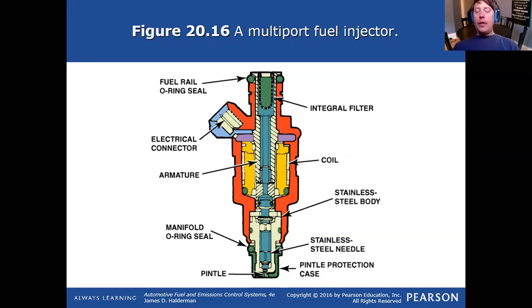That's one of the ways that injectors can go bad. If the injector pintle becomes carboned up, it's like you're partially blocking the outlet of the injector. So fuel isn't going to come out in a mist, it's going to hit that carbon and bounce. As it does, it's going to turn into a dribble or a droplet or just a straight liquid form. And that won't burn.